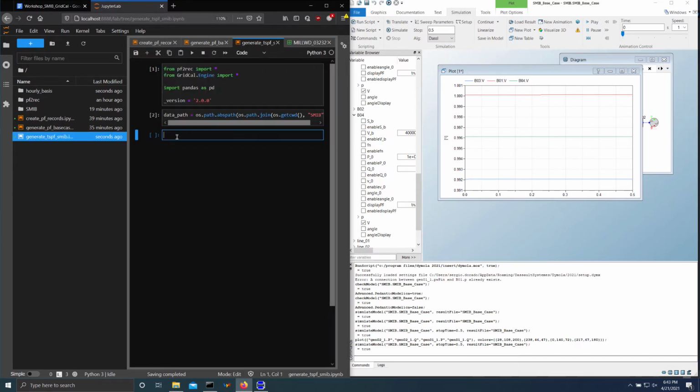So in order to do it, what we will do is to read those CSV files. So let's use one CSV file for varying the active power of our load and another one to vary the reactive power. In this case, for the active power, we will read the CSV file on an hourly basis for, let's say, New York City. And for the reactive power, let's do the same, for instance, hourly basis, the capital region.